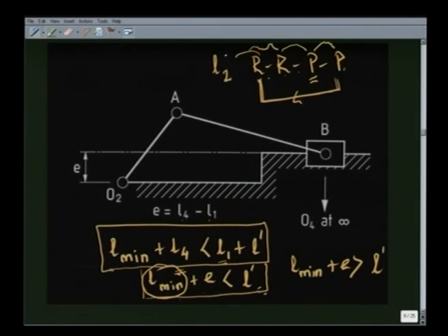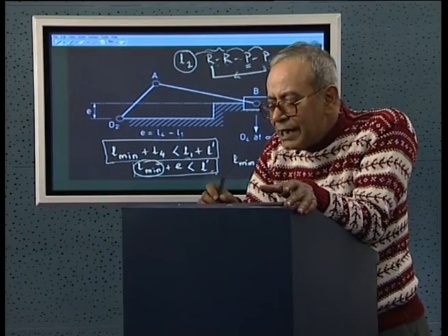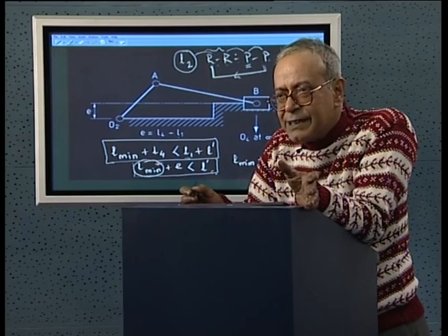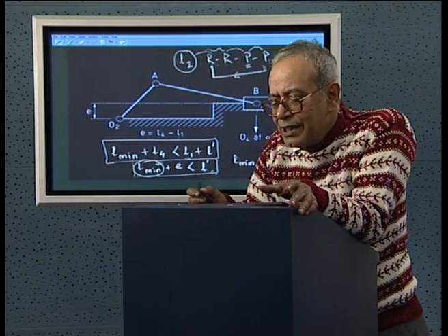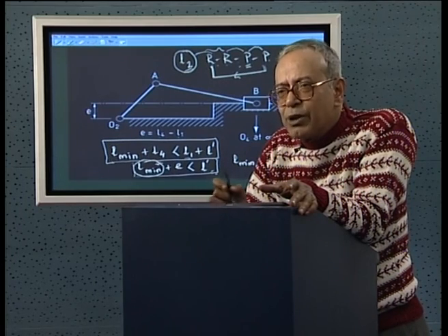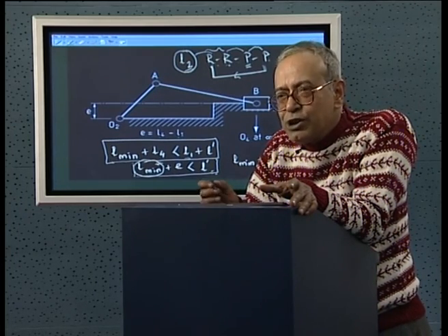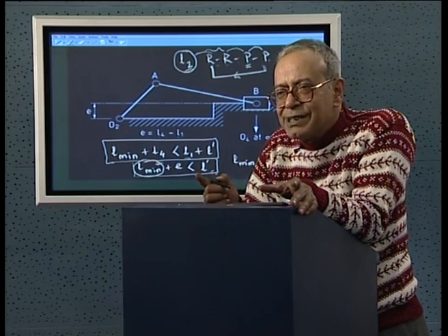So, there is one kinematic dimension, that is, one link length connecting two revolute pairs, and all other link lengths are of infinite length. Consequently, Grashof's condition is always satisfied. As a result, the shortest link L2 will be able to make complete rotation. As we have seen in the Scotch-Yoke mechanism, the crank was always able to rotate completely, or the other two links you find in the elliptic trammel and Oldham coupling, the shortest link was able to make complete rotation with respect to all other links.